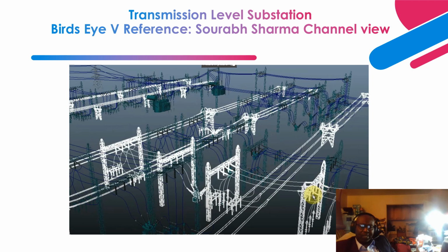This picture gives you a much deeper look. On the high voltage side, let's say 115 kV, 230 kV, 345 kV, 500 kV, or 765 kV, depending on your level of voltage for your design, you're coming in. Remember I made mention that right at the entrance these are the surge arresters that protect the substation, making sure you don't have any extreme overvoltages that will end up destroying the equipment.